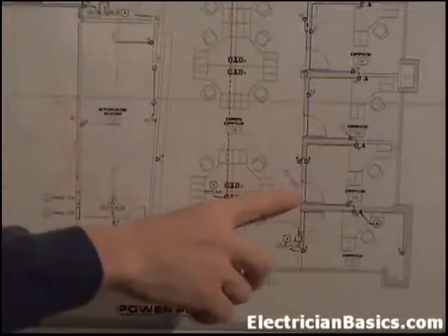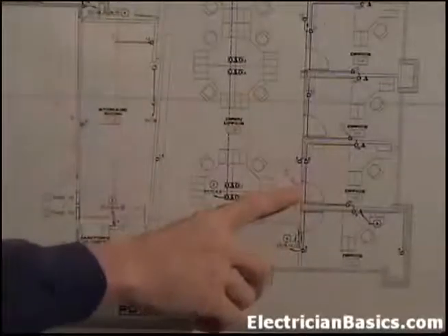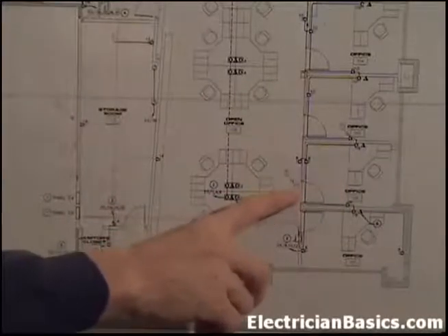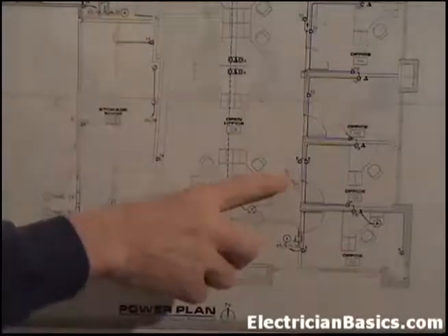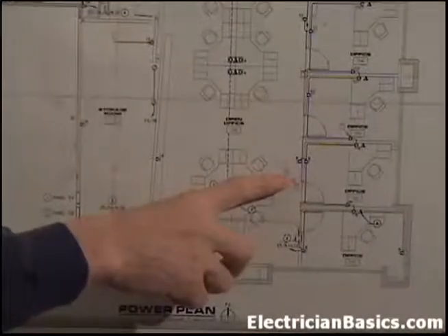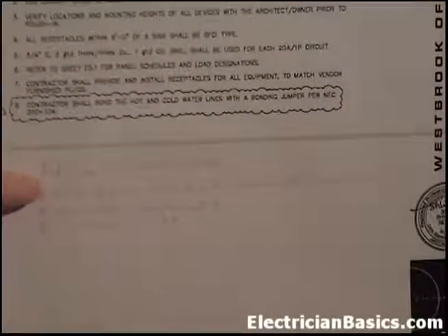And it's pointing to a box with a J in it, and I made that a junction box. You don't have to put a J in there, it's pretty understandable typically, but I also made a symbol note for that. But let's check out what keyed note 1 says in our red line notes. Here we are at our red line notes and symbols. Keyed note 1 says home run E5 circuits 2, 4, and 6 junction box on wall underground conduit to Walker duct. So that's describing that installation.